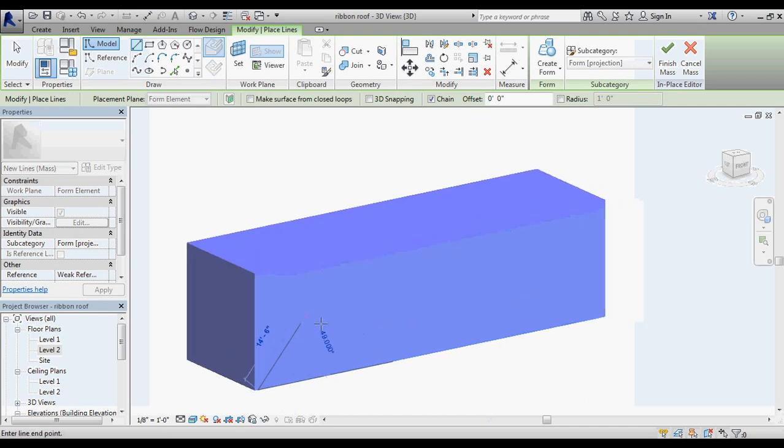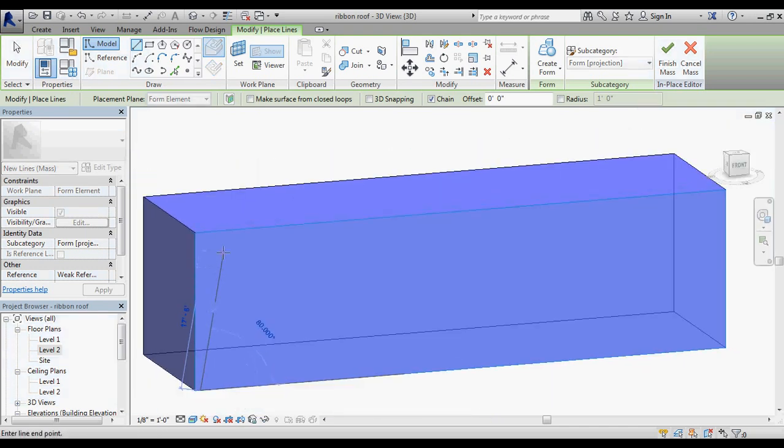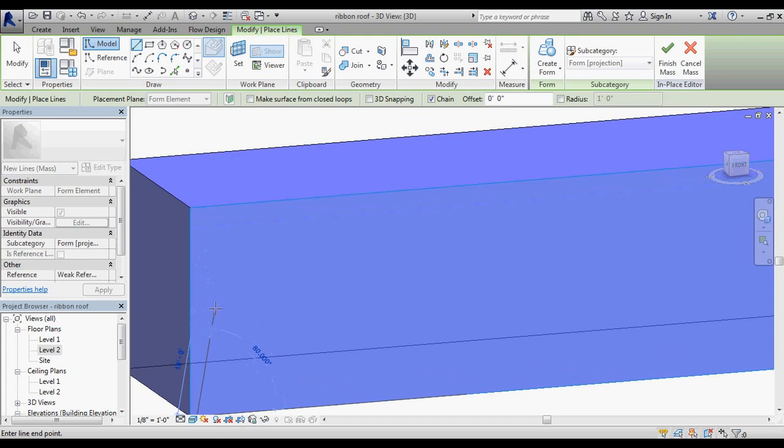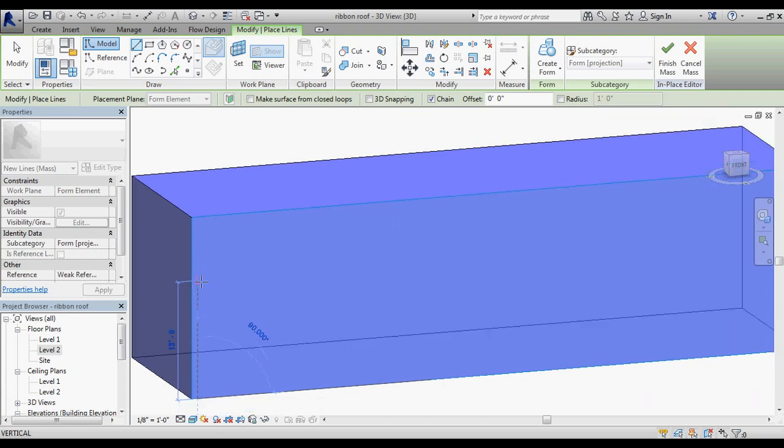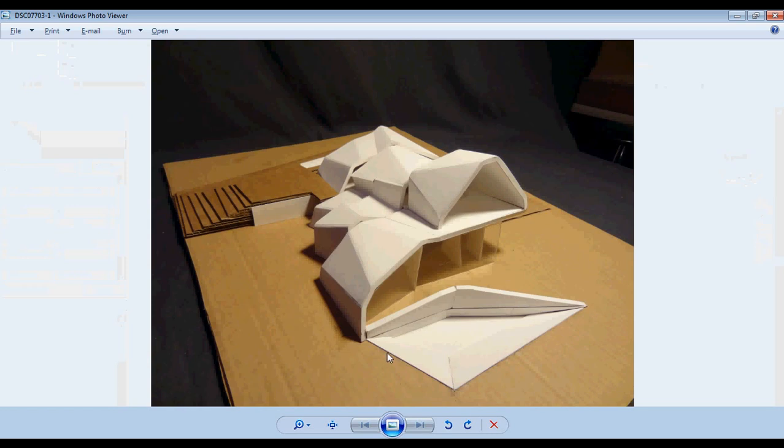And if you notice, I'm going to make a slight change to the design. The roof tool, the roof by face tool, doesn't particularly like a straight up and down line to do a roof by face. It just won't work, which is a little bit unfortunate. But let's just think about the design evolving a little bit. I don't know that being a vertical straight up and down line is completely critical to the design.